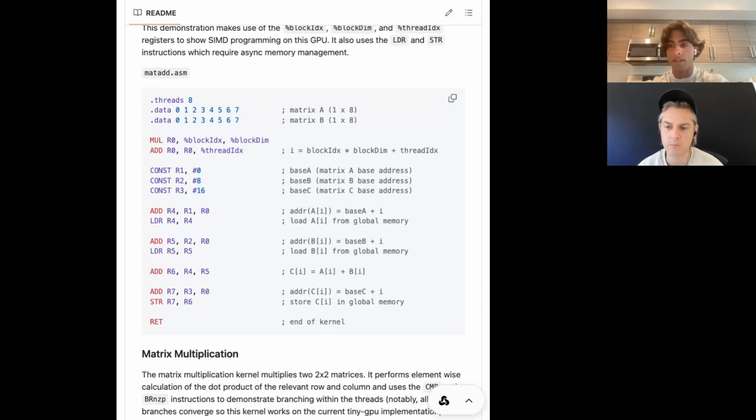And if you have a way to do that, then within that hardware, the hardware can know something about its own context. So let's say the hardware knows which thread it's executing. Now the hardware can say, hey, there's this instruction here that's supposed to load this data in from memory. The data that I want to load in is actually based on which thread is being executed here. So if I'm currently executing thread number 0, I want to load in the 0th element of A and the 0th element of B. If I'm executing thread number 1, I want to bring in the first element of each, and so on, and I want to store it in the first element of C. And so that is the most important thing here.